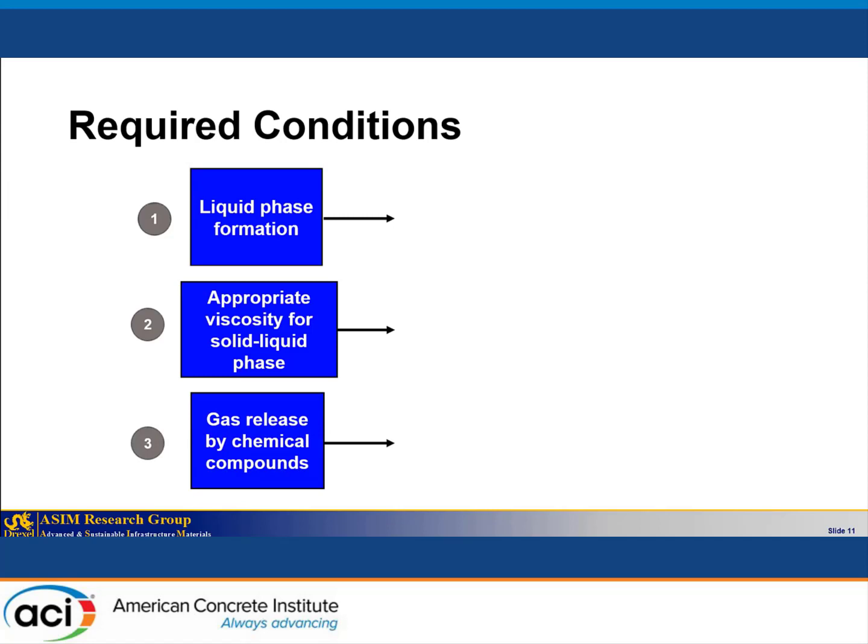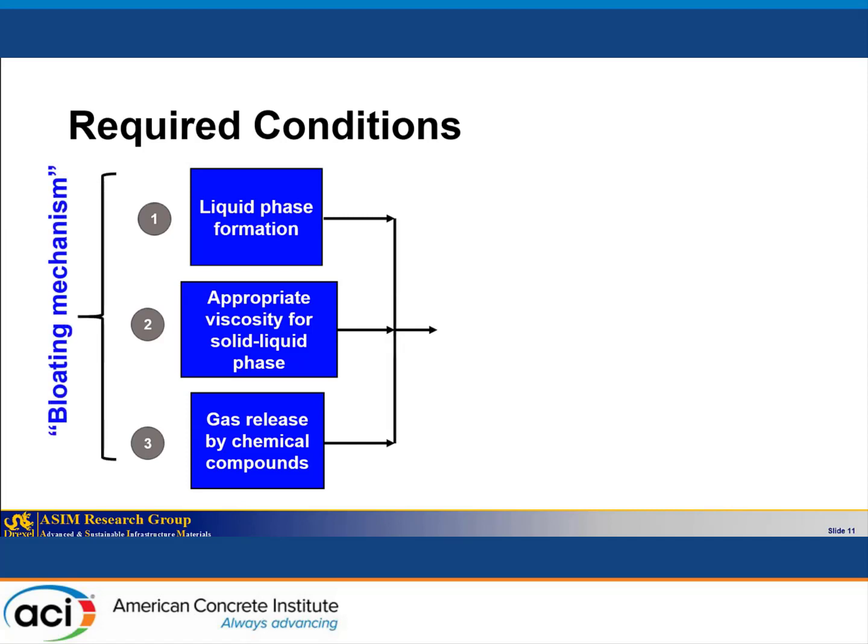And finally, we need to make sure we have some gas release by the material to be able to form the pores in the lightweight aggregate. Having these three harmonized, we're going to have the bloating mechanism occur in the lightweight aggregate. So how do we quantify these